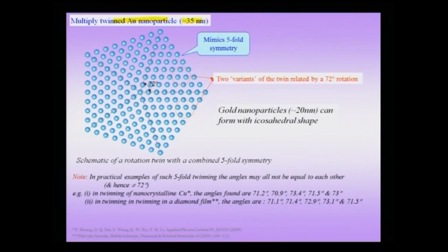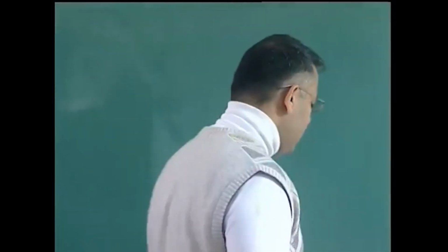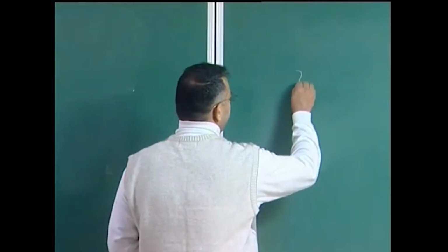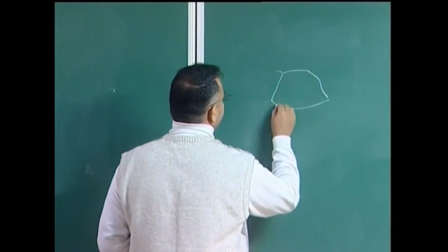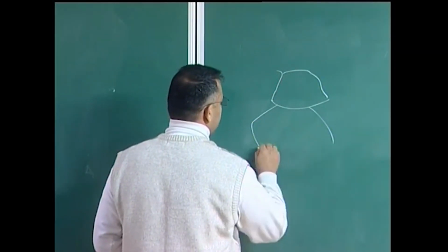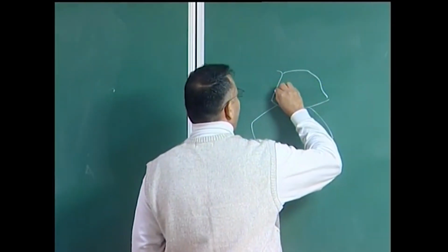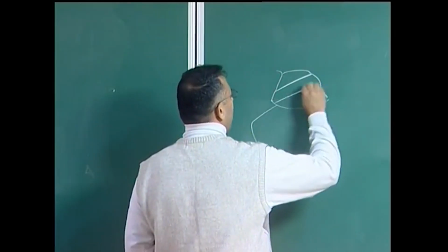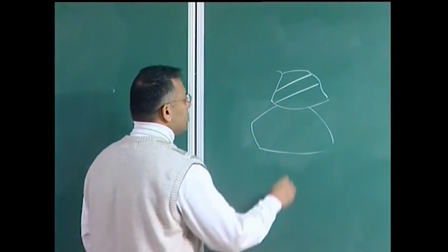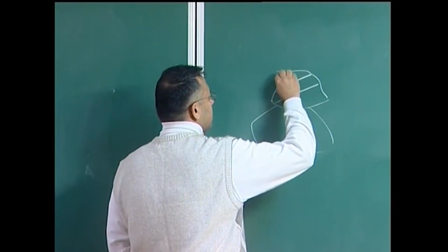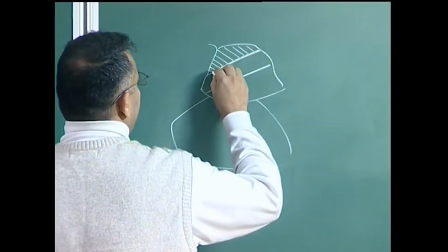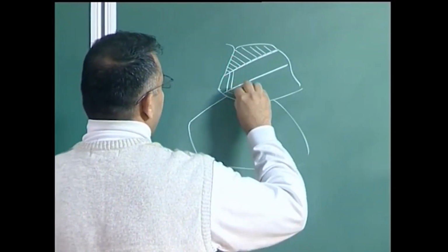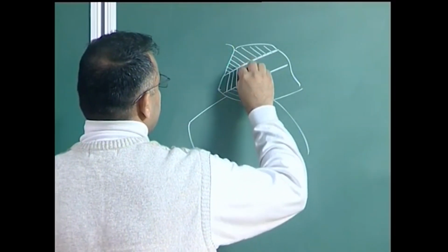Suppose I have twinning occurring in a bulk crystal. Typically, some of these twin boundaries would, for instance in a copper crystal, extend from one grain boundary to another. So, let me draw that schematically here. Suppose I am talking about a copper polycrystal. So, I have a grain structure like this, and I may notice that within a single grain you may have one twin boundary and, of course, another twin boundary extending from one grain boundary to another. So, suppose I have crystallographic planes here. These crystallographic planes would be reflected here by this, and this other twin would actually restore my orientation.